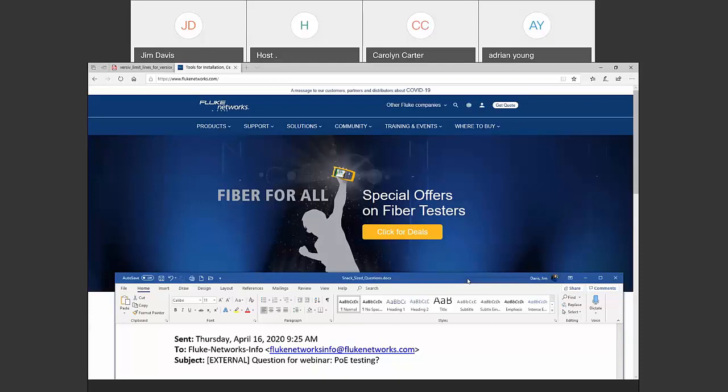Yeah, this question came up when we hosted a BICSI regional meeting here at Fluke. Once I started talking about this, everybody suddenly woke up again, because the question was, is this a requirement in the standards? I said it's a requirement on the manufacturers making the components. But if you want this as an installation test, you're going to have to specify it as an additional test. If you just say, I want Cat5e, you're probably not going to get this test. You actually have to call it resistance and balance as an additional measurement requirement.